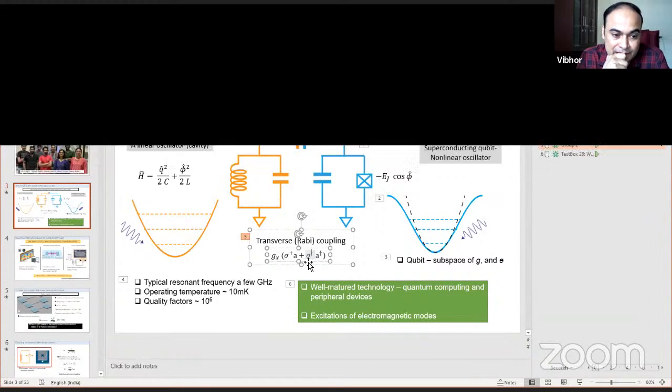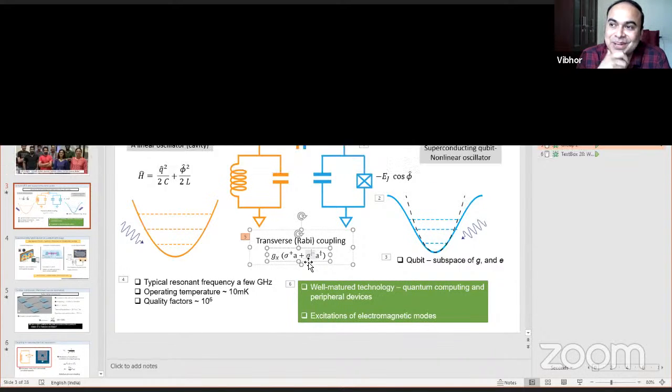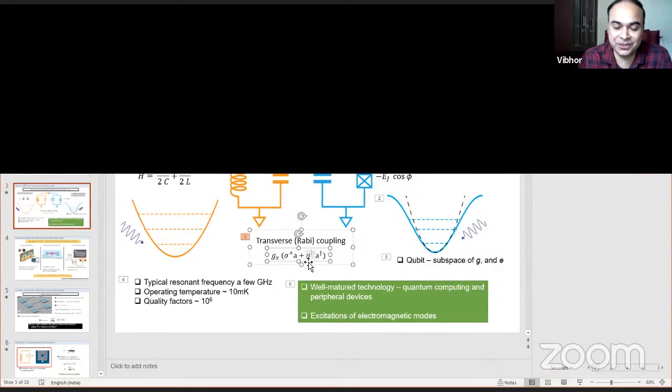My question was how easy it is in terms of your way. So it's difficult for me to answer without knowing the actual Hamiltonian you have in mind. Typically the strategy people follow, if you have some custom Hamiltonian and you want to engineer it with superconducting components, is you can take two approaches. You can have all the nonlinearities placed in the circuit in a static form using junctions, or you can try to engineer it with parametric pumps. Unless you clarify what Hamiltonian you have in mind, it's going to be difficult for me to give a general answer.